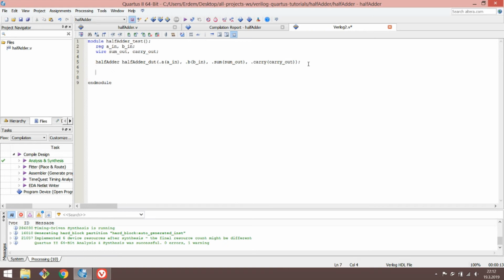The purpose of writing this test bench is to simulate something in an autonomous way. Instead of giving signals by hand, we will just write them in a text file and read those lines into the testbench code. We do that at the initial run of the testbench. So write initial, begin, and end.